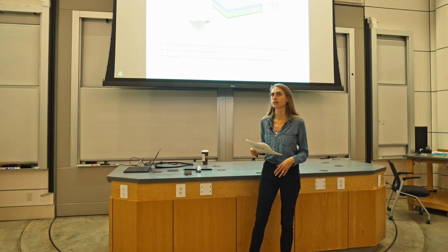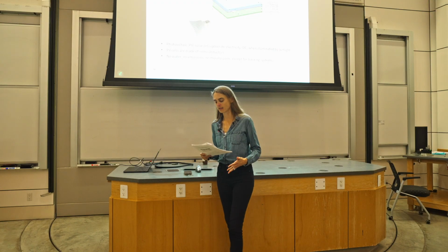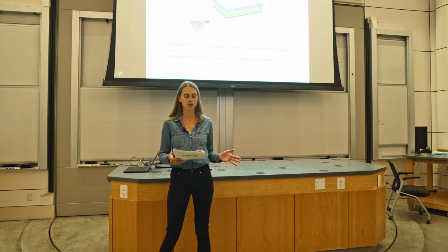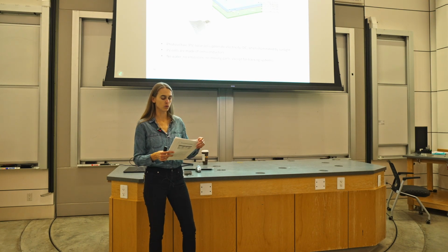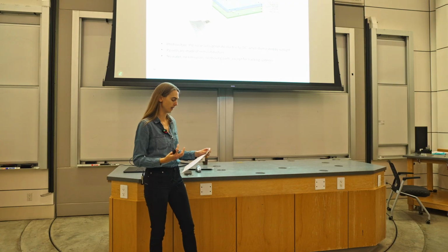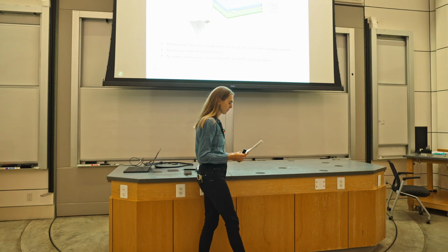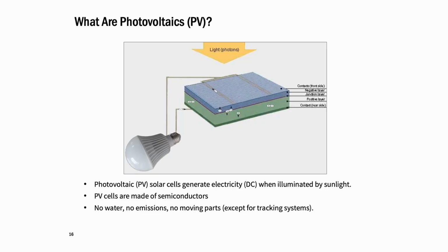Certain materials like semiconductors exhibit a property known as the photoelectric effect that causes them to emit electrons when they're hit by sunlight or photons. So a PV panel puts 2 layers of semiconductor materials together that each have different impurities introduced into them through a process called doping, where one layer of the material is doped to have a spare electron, and it's known as the N-type or negative layer.